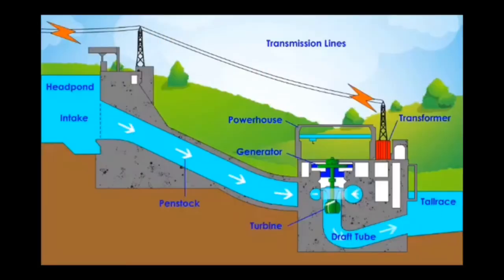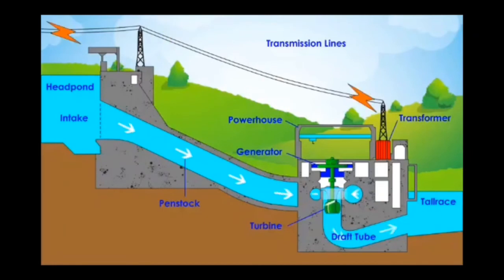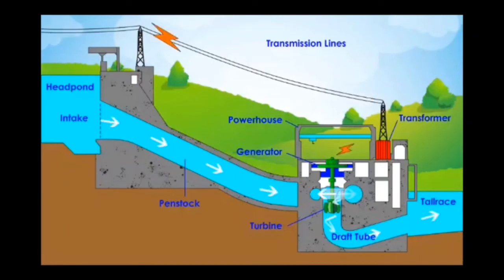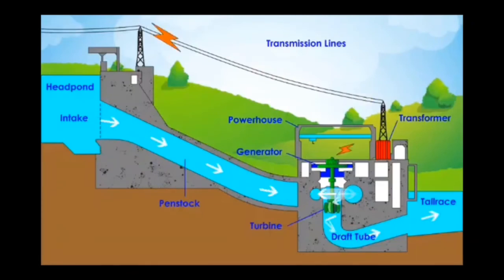Operation and maintenance for hydroelectric power plants: the maintenance of the hydro power plant can be categorized into two parts. First, preventive maintenance and corrective maintenance. Preventive maintenance can be classified into planned, conditional and predictive maintenance, whereas corrective maintenance is employed in an emergency.